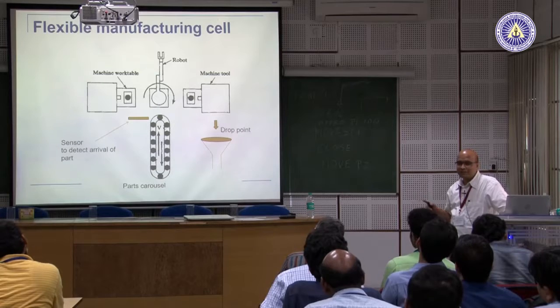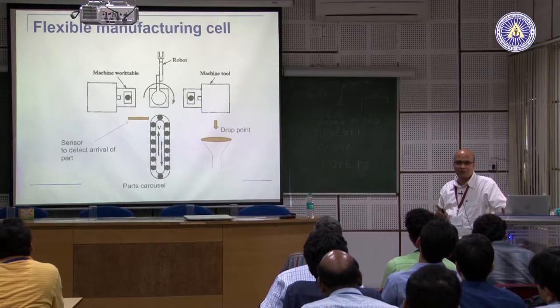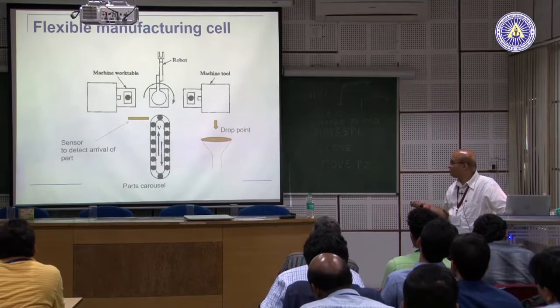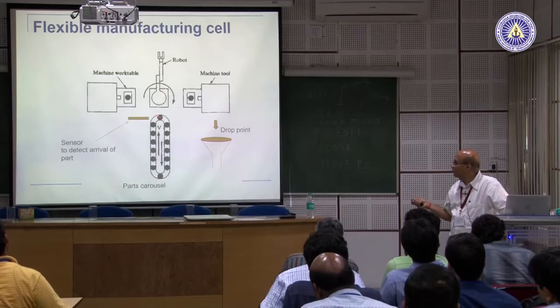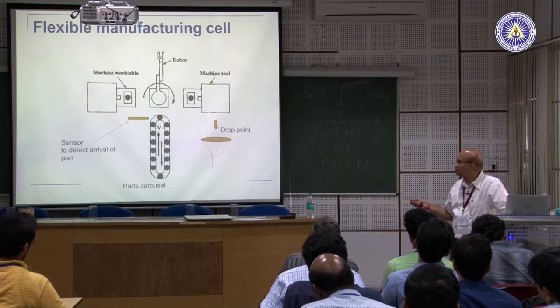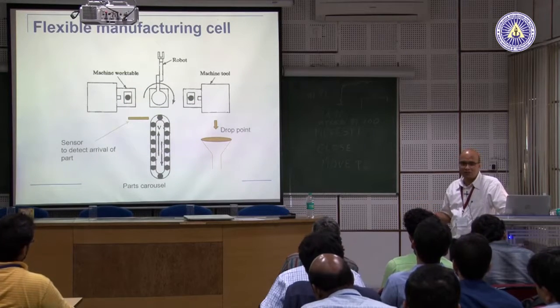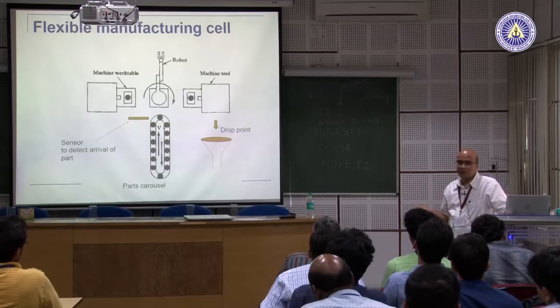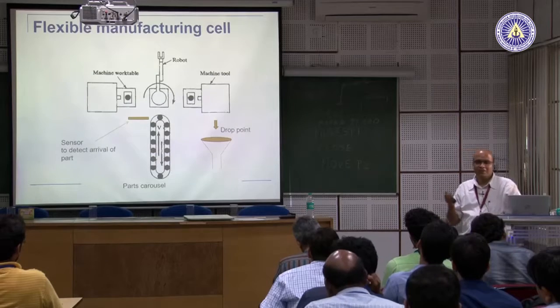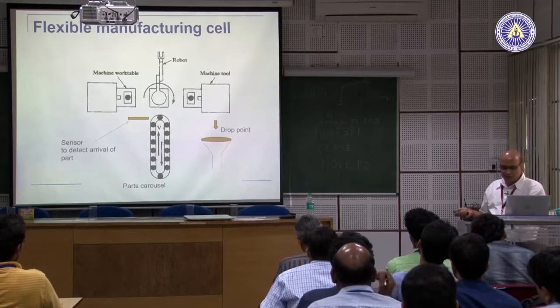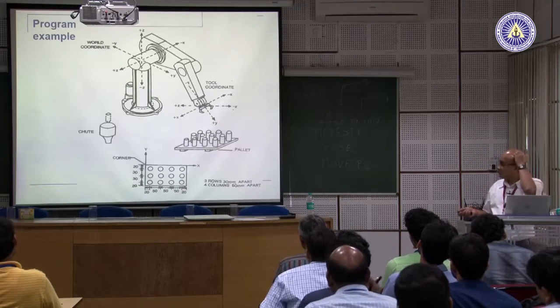At every time, you have to sequence the timings properly, because what can happen is, for example, if both these two parts are on the machining center, machining table, and the robot picks up something there, now it cannot take up this one and put it there. So, it is deadlocked. This kind of deadlock can happen in many ways, and we have to be very, very careful that it is not deadlocked. So, this example looks simple, but is not very simple. This one is a simpler example.